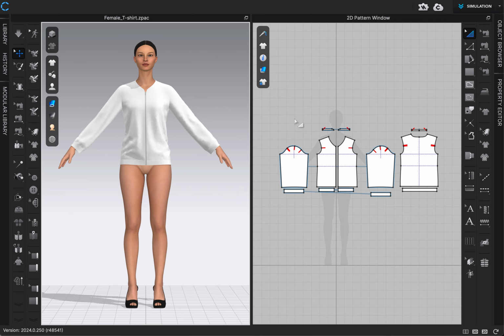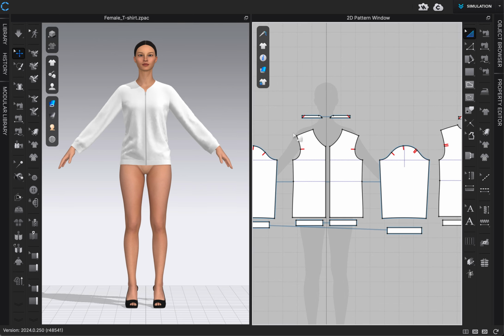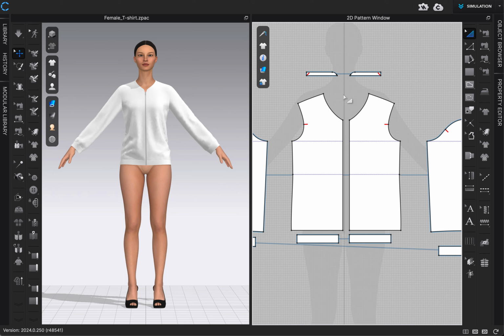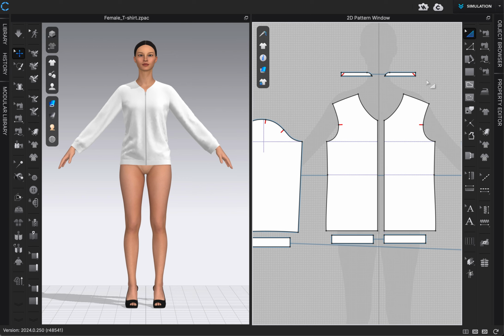So the first part, for those uniform quilting lines that are consistent, we're going to be using the fill tool. And so how we start out is we first need to add internal lines onto our pattern that are going to become our quilting lines. So to do that, the easiest way is to first just offset our pattern outline as an internal line.